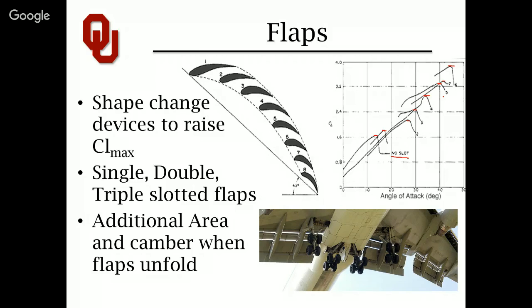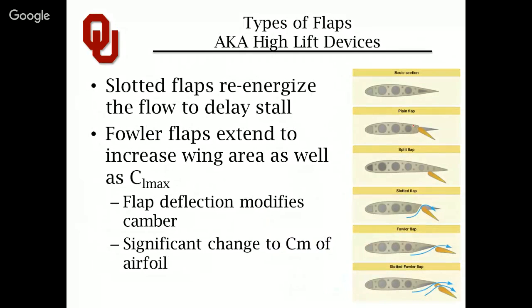You see that you almost reach a naturally occurring coefficient of lift of 4.0. I mean, with a default airfoil, you're doing very, very good. Without any flaps, you've reached 2. So something is happening with these slots. As you continue to add slots for air to pass through in these Venetian blind type arrangements, you're able to reach higher and higher coefficients of lift. This comes with penalties. You'll understand more so whenever we get to 3-dimensional effects, but it's an important result to see at first. There are many types of flaps.